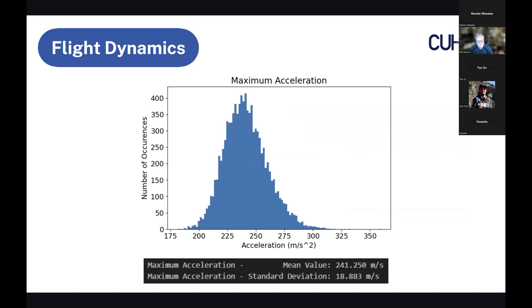We chose RASAero because it can include the environmental data of the launch site. It can import real-time and forecasted data that we will use prior to the competition, and we can compare the result to OpenRocket and RASAero to verify the simulation result.